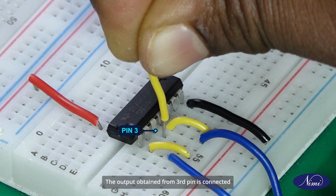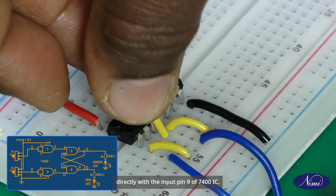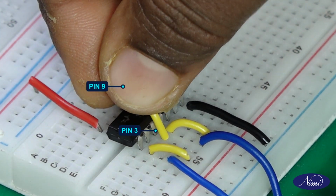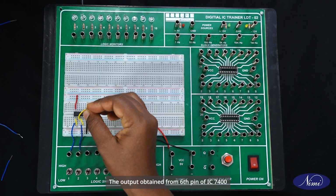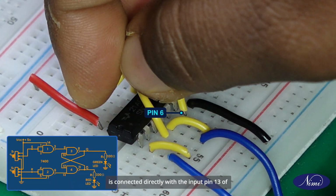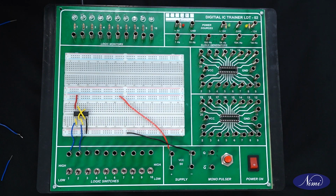The output obtained from the third pin is connected directly with the input pin 9 of 7400 IC. The output obtained from 6th pin of IC 7400 is connected directly with the input pin 13 of IC 7400 respectively.